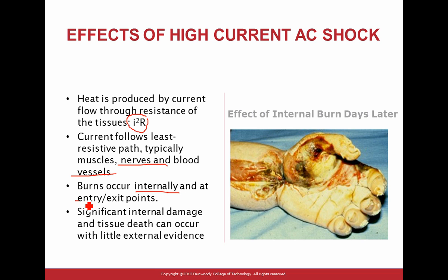Internal and external damage. Internal damage can happen to you guys because the current goes right underneath you. So your skin could look good, but internally you're burned. There's significant internal damage and tissue death, with little external evidence. So be aware of that one. The point of entering the current and the point of exit the current typically is where it's very obvious when you see shocks.